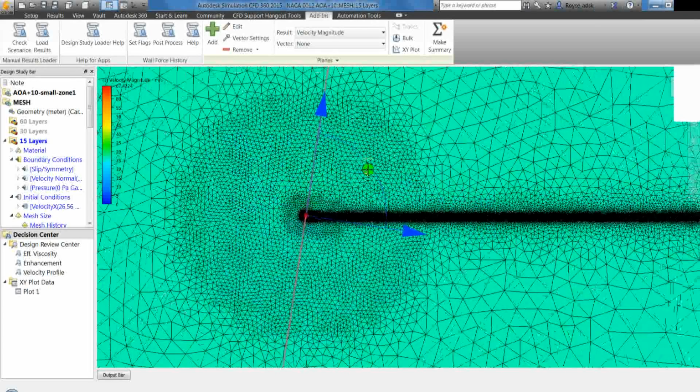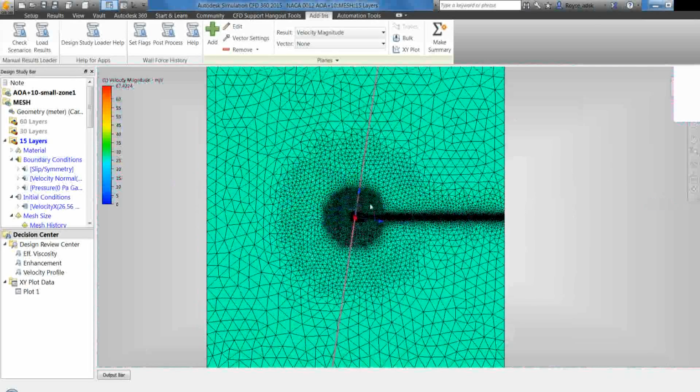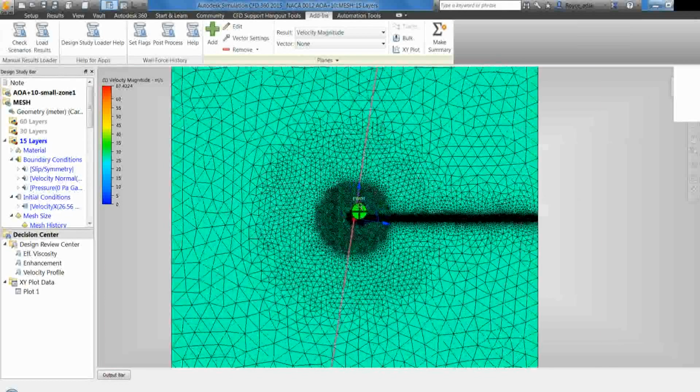Okay, so you can see now going into Simulation CFD. In terms of the meshing strategy, if there's no gradients, you don't really need a whole lot of mesh. So as you work your way out, you're going to have a very coarse mesh throughout most of the domain. And then as you can probably see, there's a little bit of a refinement region. Looks like a target, and then you start getting another refinement region, another and another.